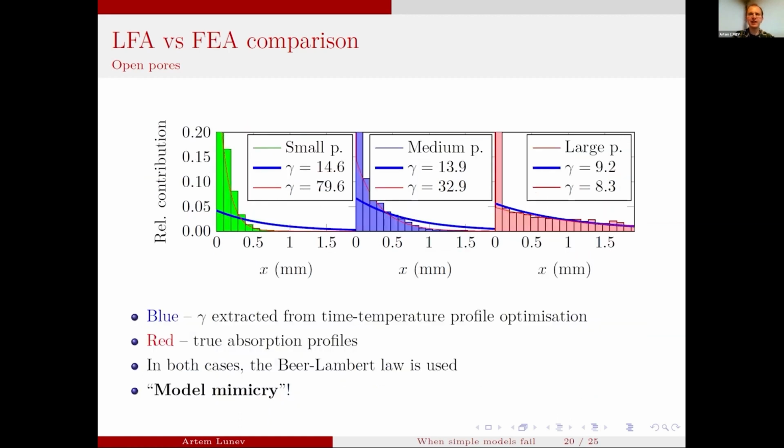And when we compared the prediction from the inverse problem, here you can deduce the gamma factor as the calculated parameter by optimizing the four different parameters that you have for the macro scale heat conduction, where you assume a homogeneous sample with four parameters including gamma, and then you try to vary them and select the best fit to the actual FEA data.